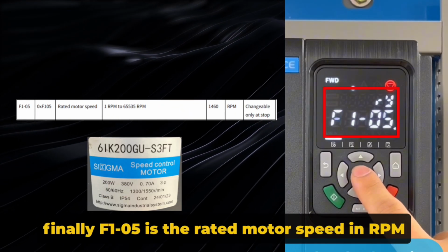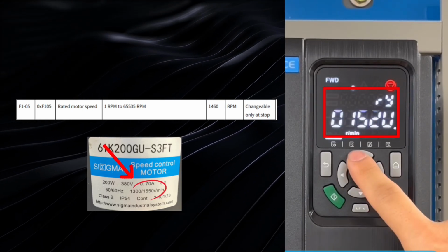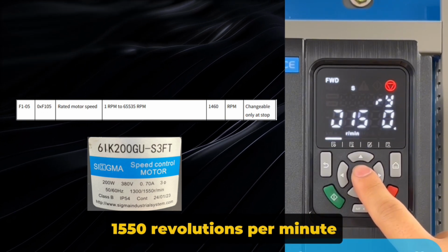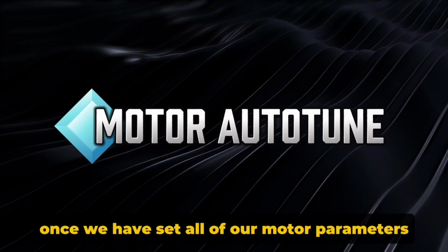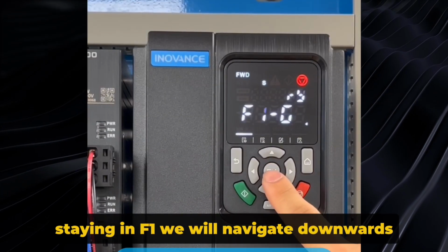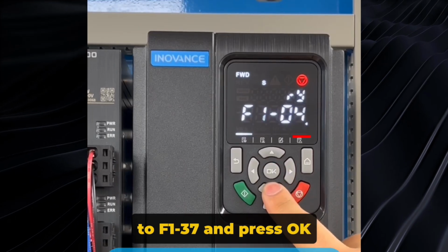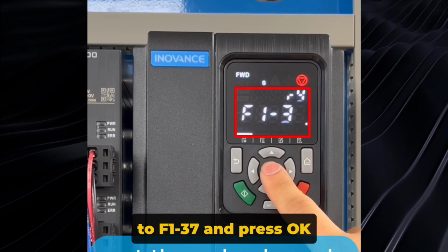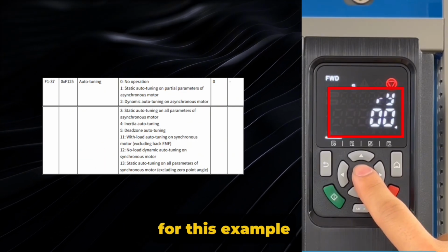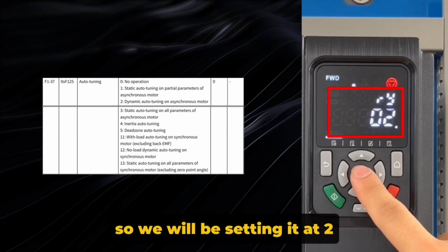Finally, F1-05 is the rated motor speed in RPM. In this case, it will be 1550 revolutions per minute. Once we have set all of our motor parameters, we will now auto-tune the motor. Staying in F1, we will navigate downwards to F1-37 and press OK. Set the value based on the type of motor being used. For this example, we will be tuning the motor dynamically, so we will be setting it at 2.